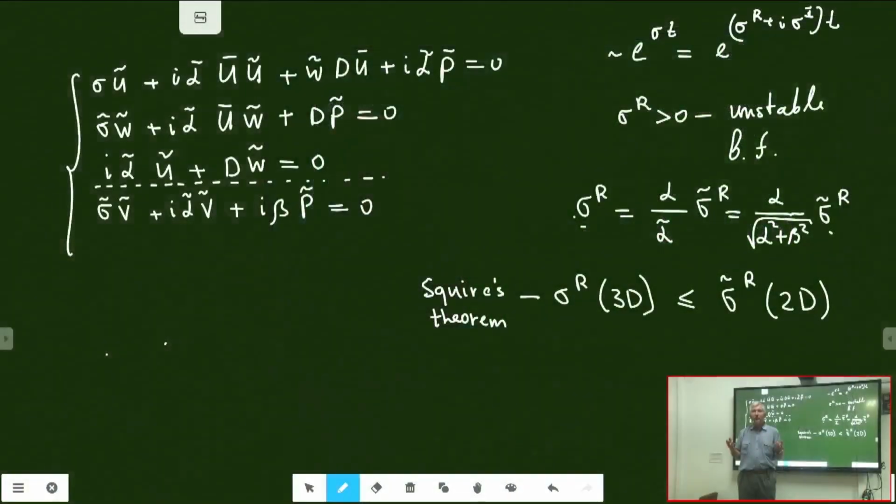So what you will do, by introducing the stream function, you will get rid of one of the equations. The continuity equation will be gone, but you will introduce higher order derivatives in the equations. And higher order derivatives require more boundary conditions. So you get rid of the continuity equation, you enjoy that, but then you have to introduce extra boundary conditions, which are extra equations. Nevertheless, from an algebraic point of view, the stream function does provide certain benefits, but a stream function can only be introduced if the flow is two-dimensional.